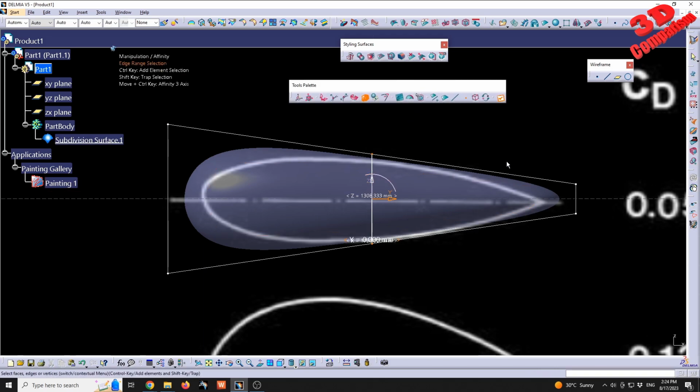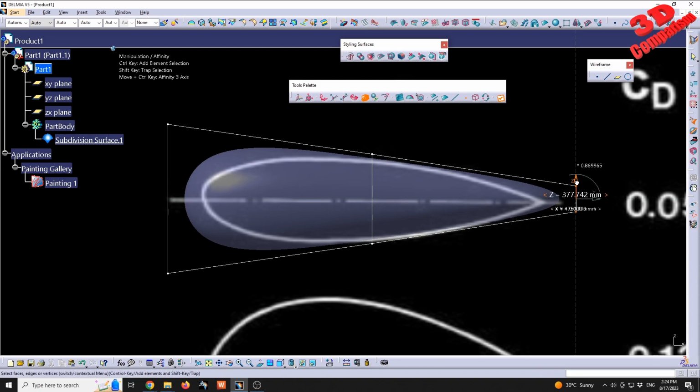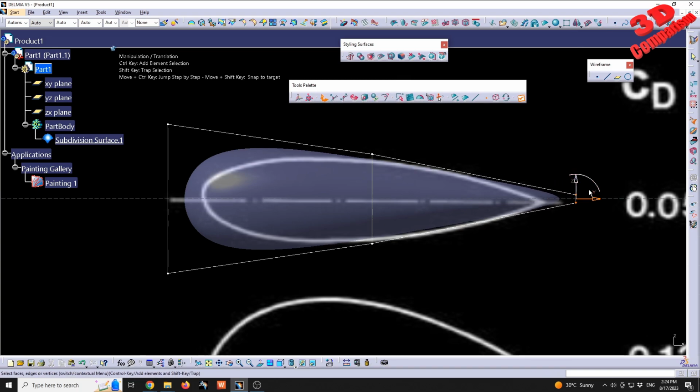So in this case, if I'm just gonna scale down the back now, we're gonna see that the front section is no longer influenced because we have that cut over there. It will still be influenced, but not that much as we can see. So we can easily adjust that, and now I'm gonna move it on the Z and on the Y axis. So that was the Z axis, and now a little bit on the Y in order to match that shape.